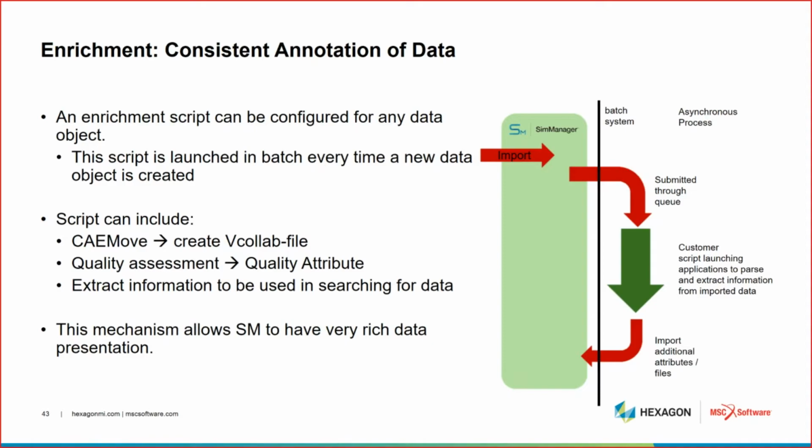And that is something that, if you've got a script to do it, we can then launch that script in batch automatically as soon as the result of the thermal analysis is done. We can then automatically launch the process of generating the data for the downstream structural analysis moving forward from there.